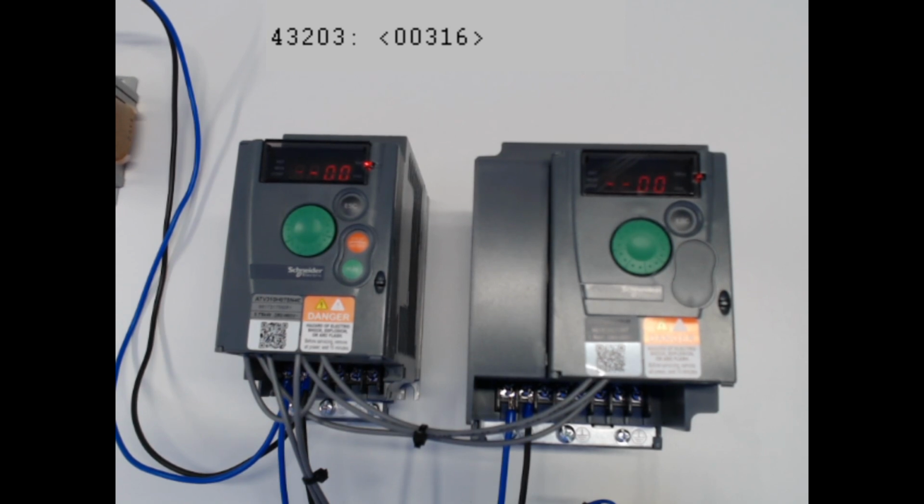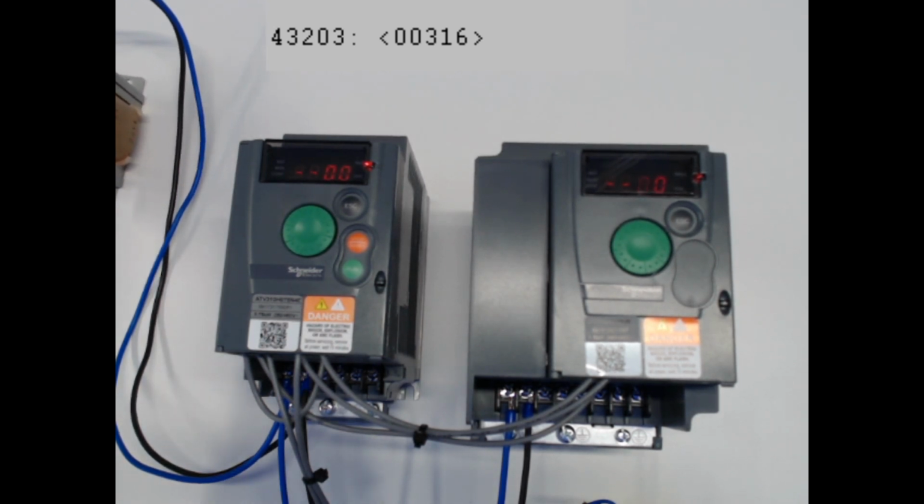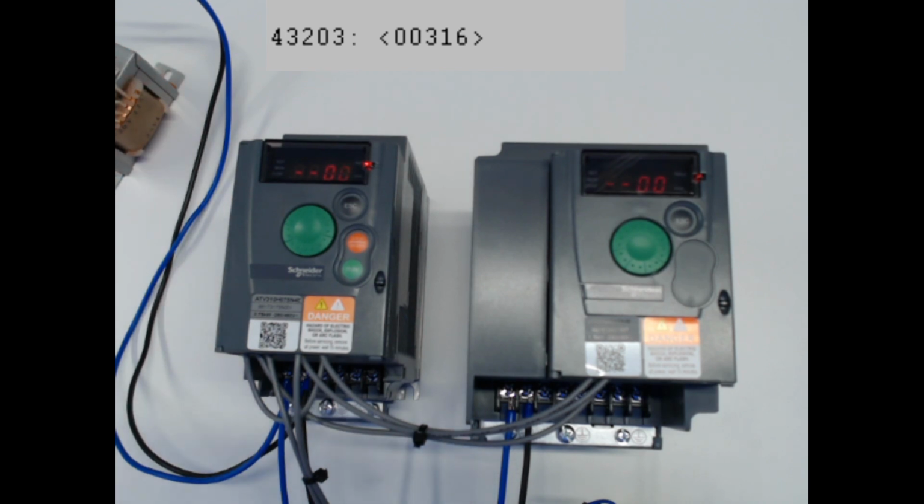They are connected to a transformer. Because I don't have 415 here, I will just use a very simple transformer. Just a quick note, if you want to try out the inverter in places without 415, you can put in 220 at the input. You just put in your line and neutral, but keep in mind that it can power up, but the IGBT will not turn on, which means that if you give it a run command, the drive will not run.